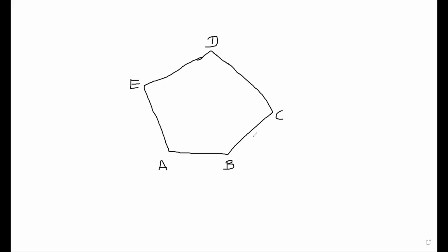And you can select any line, so this is your movement. When you measure the bearing, measure it in the forward direction. Not CB, please measure it in this way. Then this is the line you are starting, so your first line should be BC.